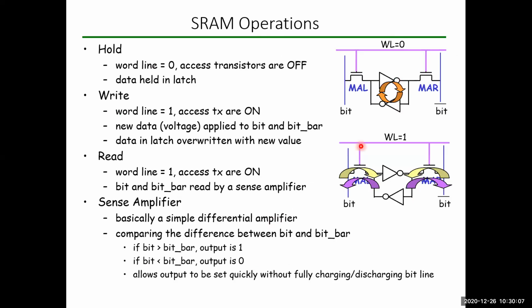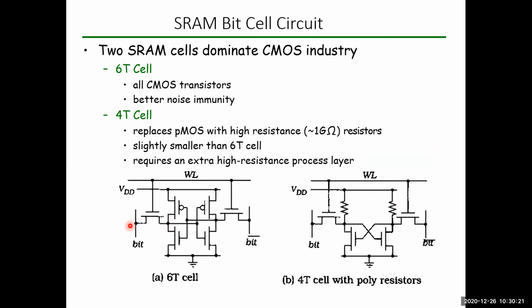In the previous diagram, we drew the circuit with the help of NOT gates. Now we are trying to draw this diagram completely in terms of CMOS logic. So this 6T cell will become a CMOS circuit where you have used cross-coupled inverters. The cross-coupled inverters have been used over here. PMOS and NMOS will make one NOT gate. Again, one PMOS and NMOS will make another NOT gate. So this is a complete 6T CMOS SRAM.